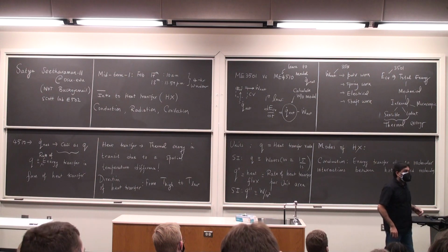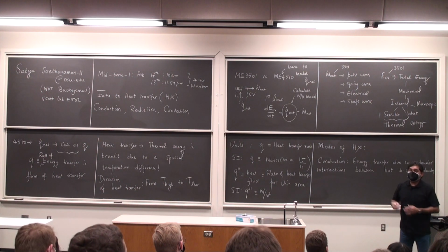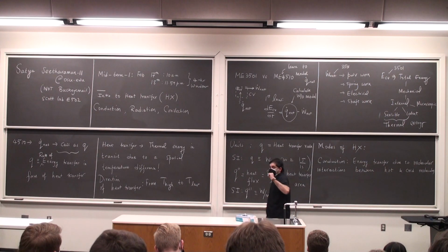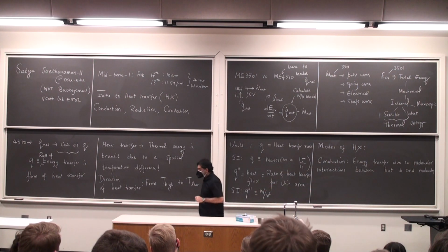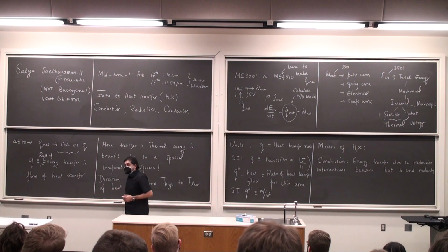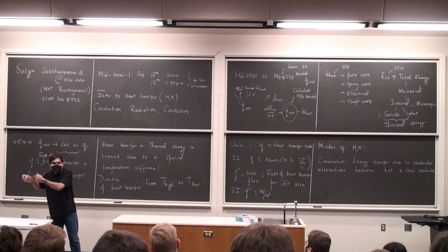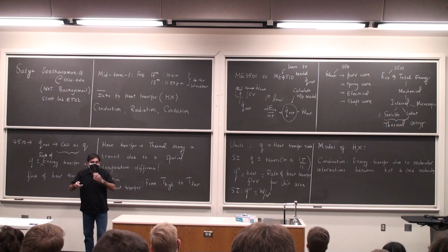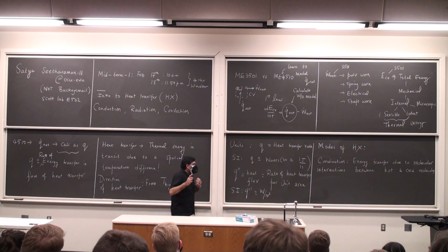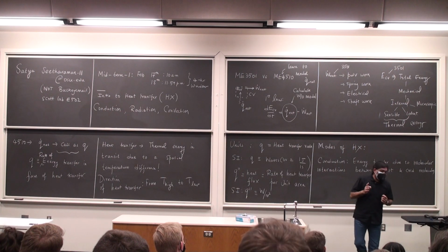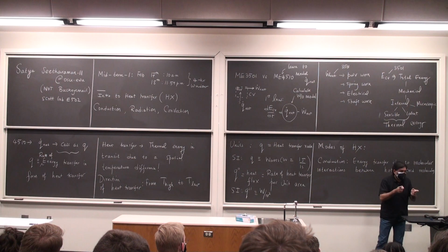It starts striking other neighboring molecules, transfers a certain amount of its energy. So if a neighboring molecule is sitting there minding their own business, this fellow comes and pushes that guy. The neighboring molecules get a certain amount of kinetic energy. This keeps transferring throughout. So this is molecular interactions. The thing you want to remember, in conduction, there is no bulk motion of the molecules.